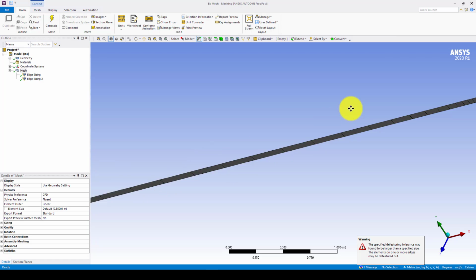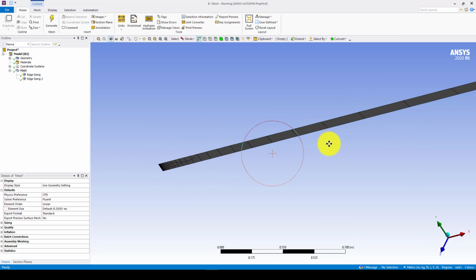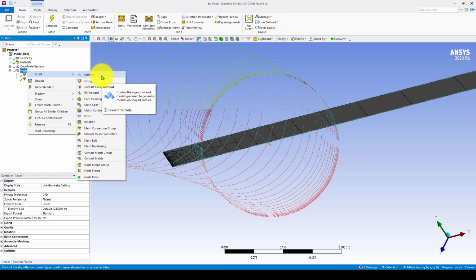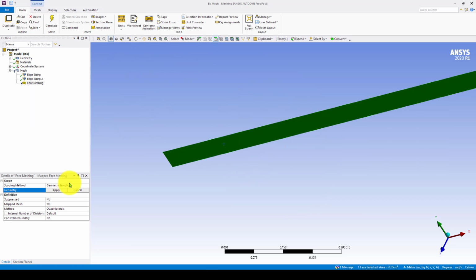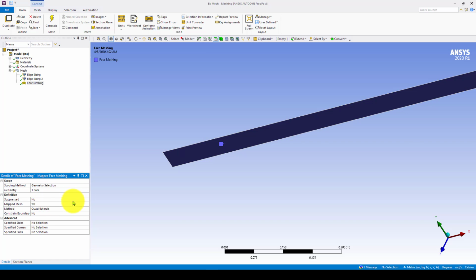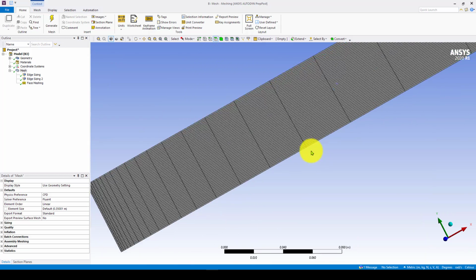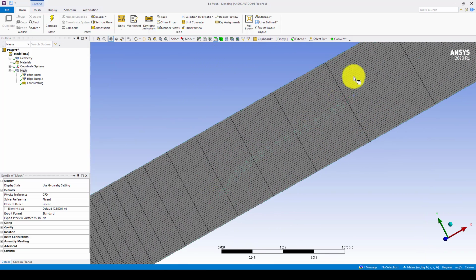So now the question is how we can control all this face. In 2D, we have the action insert here. You will see the action face meshing. So we can select the face, apply, and you choose the type of element. We want to use quadrilaterals. It's a mapped mesh. Press generate.